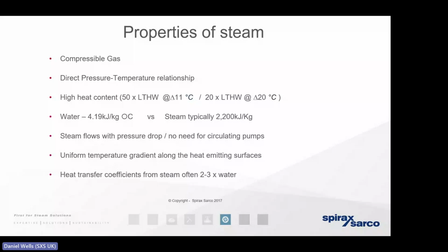But as far as this presentation is concerned, it's critically important to remember that steam gives up its heat energy by condensing. So it changes state from a gas to liquid. That liquid condensate exists at exactly the same temperature as the steam does. So when steam condenses, it gives up its energy, it changes phase, but the pressure and the temperature of the condensate remain exactly the same.